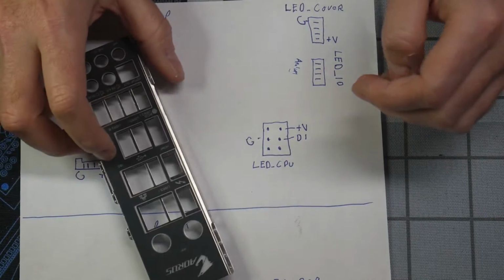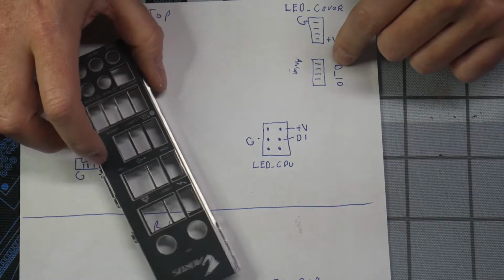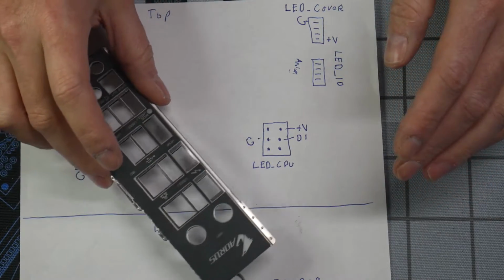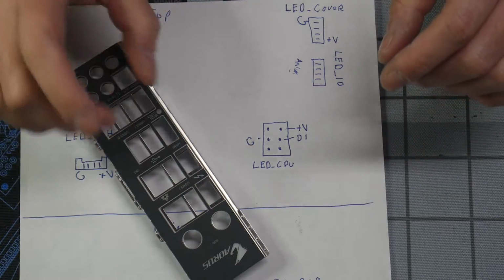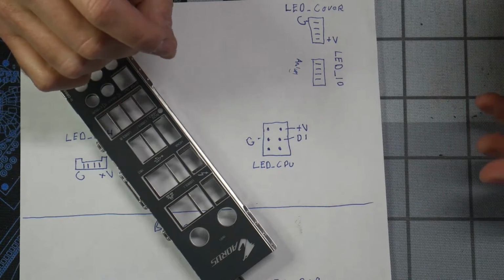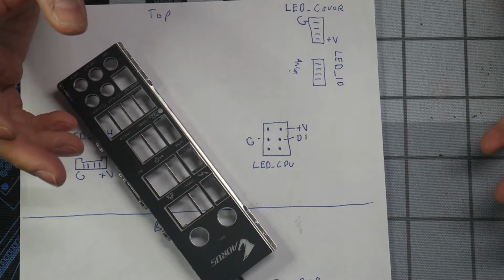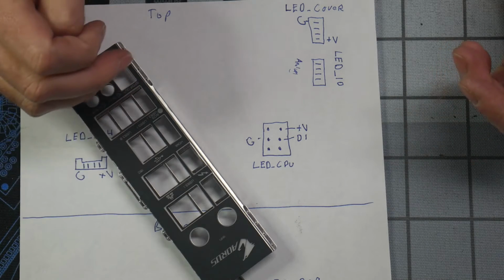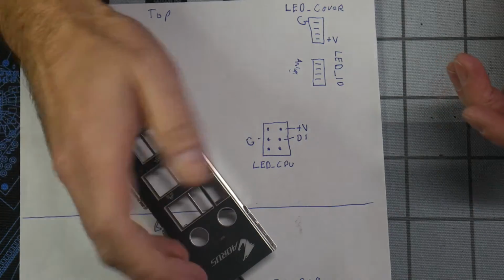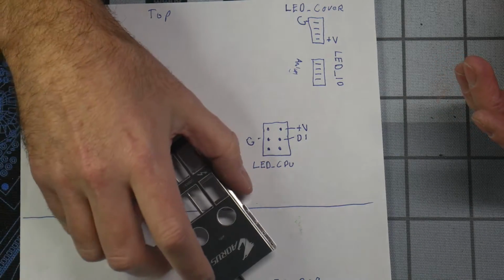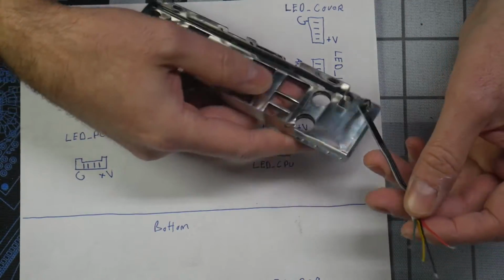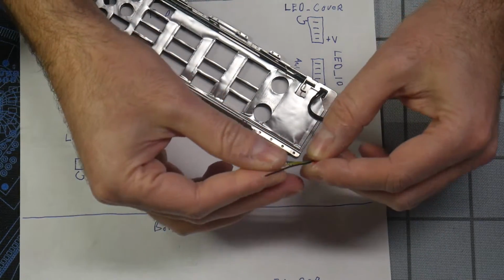This right here is an I/O, and I know this is LED I/O, so that means that this is analog. And most of the analog LEDs I've seen on Gigabyte's motherboards, in regards to the onboard, are 5V. One way you can tell is if the lighting's on when the PC's off, because only the 5V standby rail is on when the PC's off. So that's one good way to tell if it's 5V or 12V. And when it comes to using analog LEDs, there's less risk of reversing the polarity.